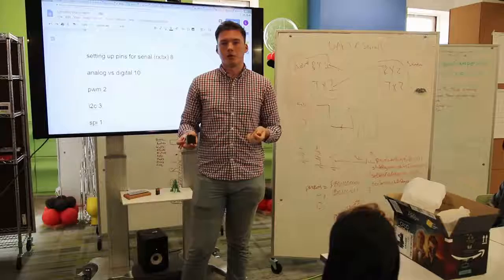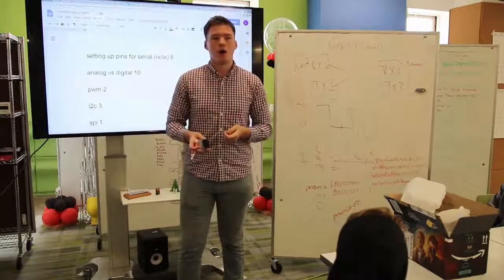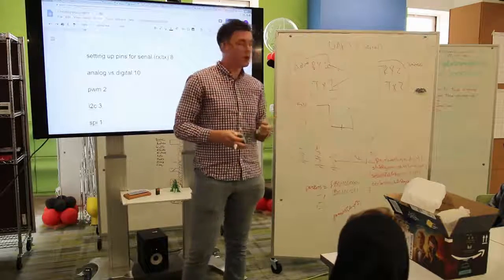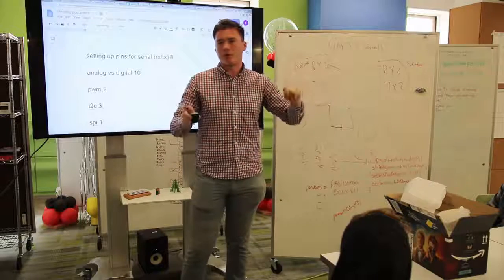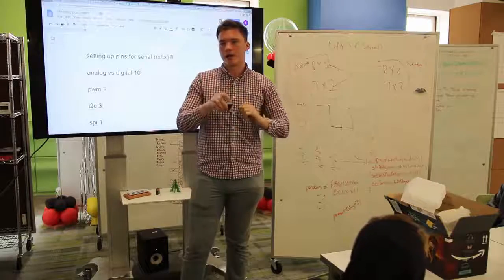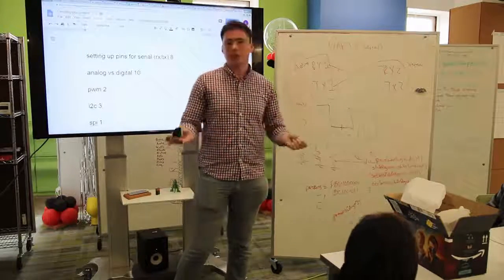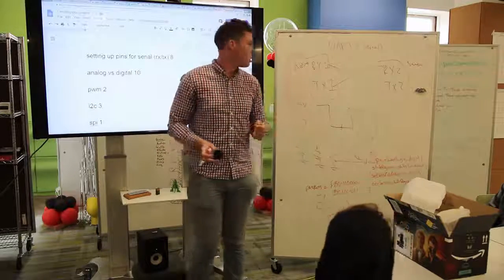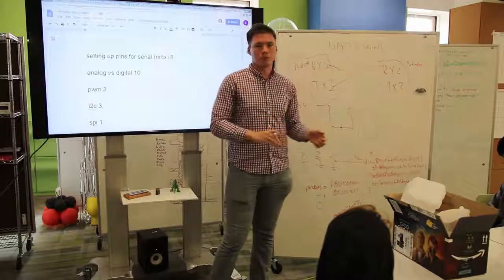For most of your applications using serial, it generally doesn't matter what rate you're using. I'd default to a lower one, like 9600, which is a standard. Why it's a standard has to do with the fact that this is implemented in hardware, so that 9600 number, that 115200 number, just works nicely with the Arduino's hardware. But it basically depends on how much information you need to get past quickly. Does that make sense in terms of how serial works?